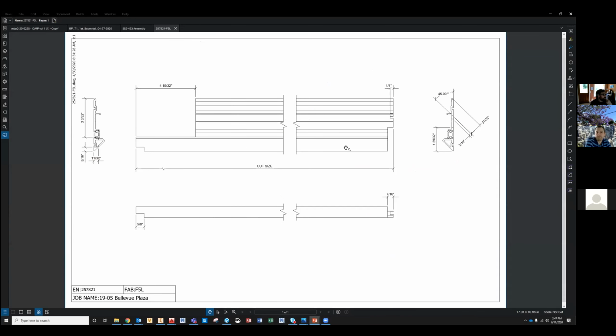So this is an Inventor-based fab drawing. You can place the part in one view, and then basically you can drag out views that you want placed, and it'll drop them in there. This is actually the part, and if you modify this part, those changes will update in your drawing as long as you're using an Inventor DWG.